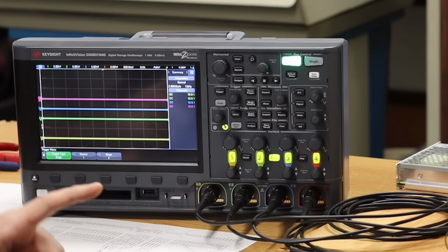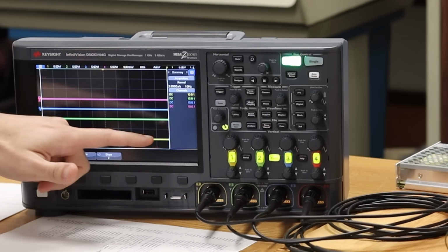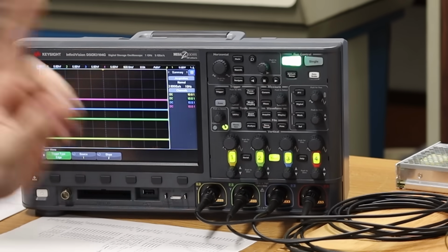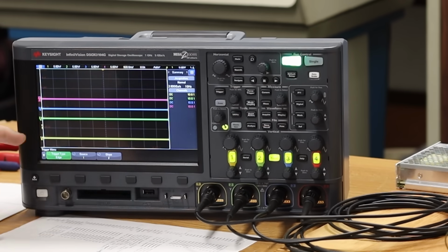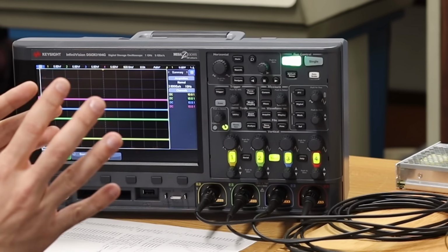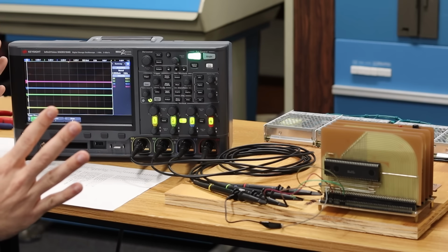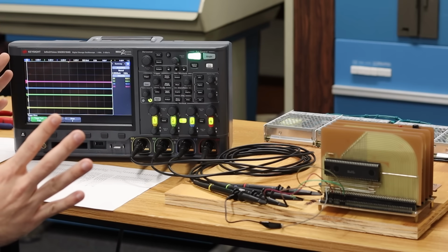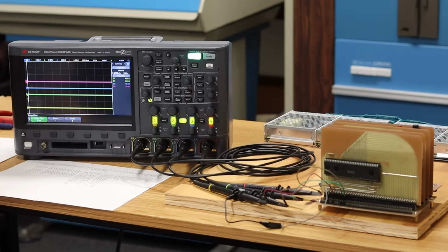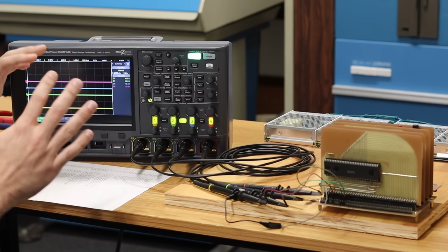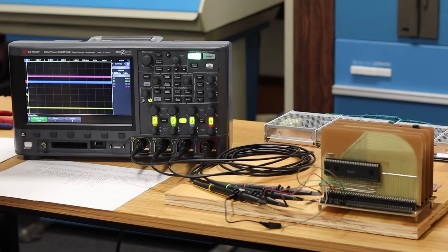Okay, I've got the scope hooked up here. The yellow trace here on the bottom is going to be the clock because we upgraded that to run at 3 megahertz. So I want to see if that's truly chugging away at 3 megahertz. Then we have the 3 address lines that should be toggling with our program. Now I'm not expecting this thing to just work right out of the gate. I'm never that lucky, and I built it, so I know that there's going to be something wrong here. But let's go ahead and flip the power switch on and at least see what's wrong.